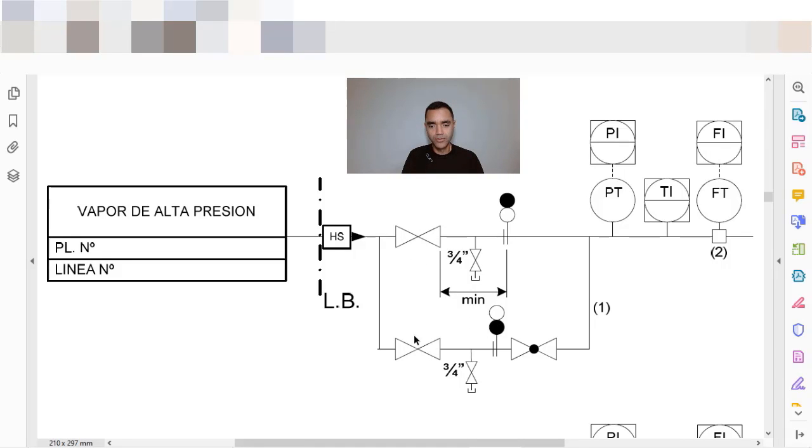Verify that during the use of the bypass, the figure 8 must be rotated, because as it is, the isolation part is in the system, is aligned to the system, and when the operation is finished, the figure 8 must be rotated again to isolate the system.